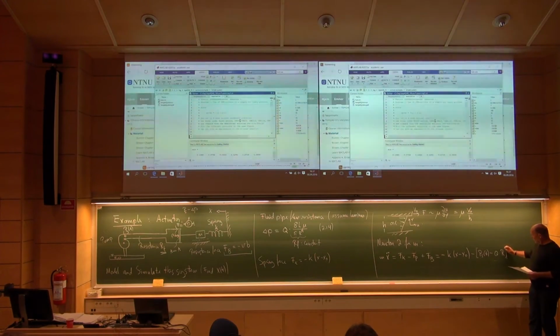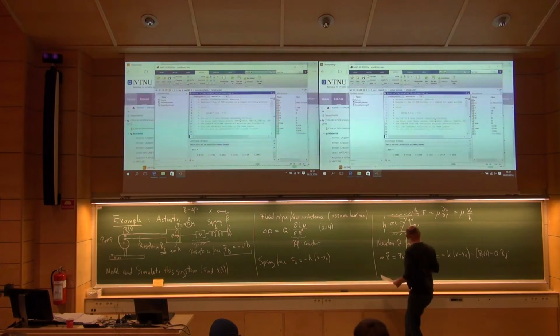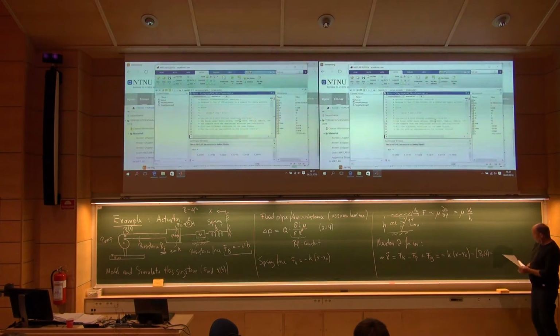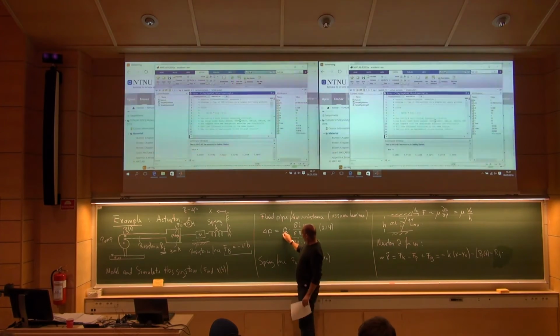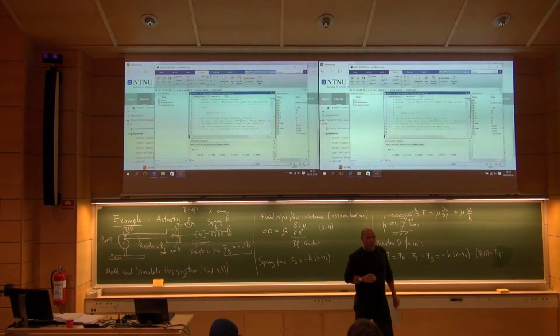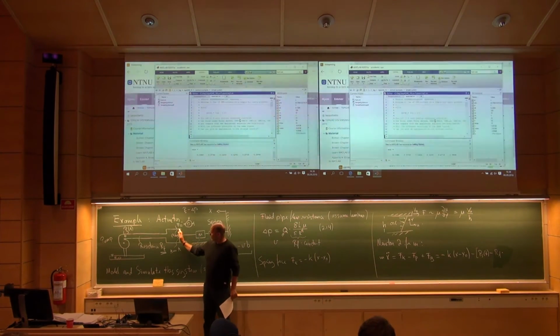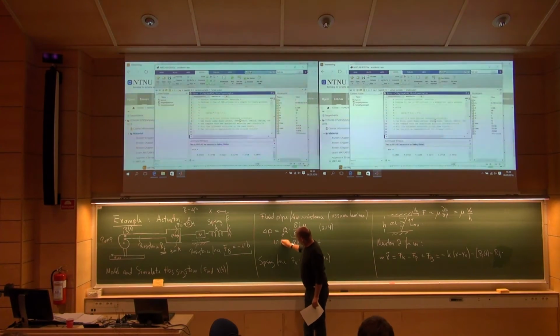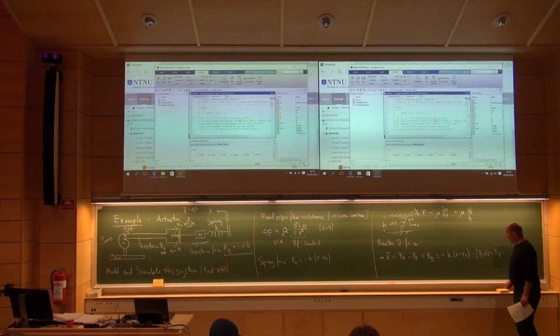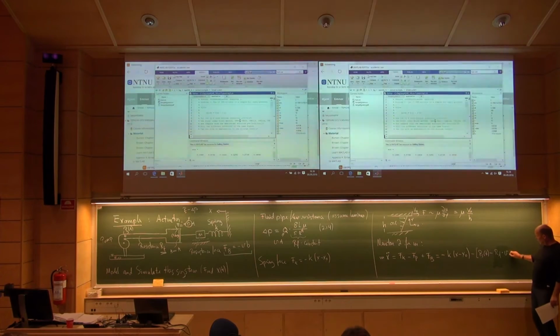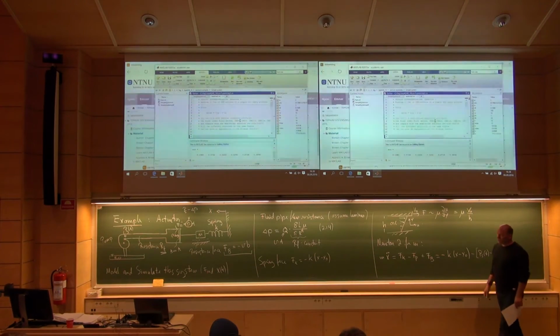Well, no, we can't use Q, sorry. F multiplied with, and what is Q? Volume flow. Well, that will be the velocity, V. Velocity for the mass will be the same velocity as this piston here, times the area. So that's the volume flow. We can call it V, that's okay, and area A. Source pressure minus delta pressure operates on the area A once more to get a force.